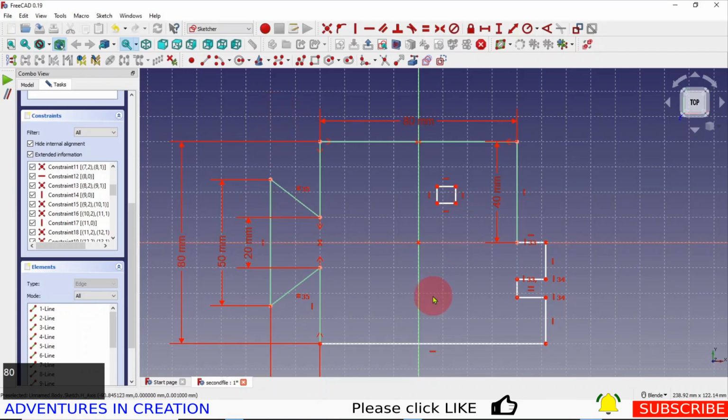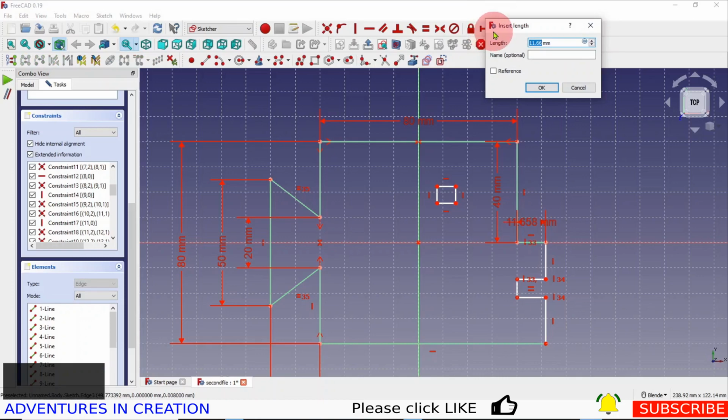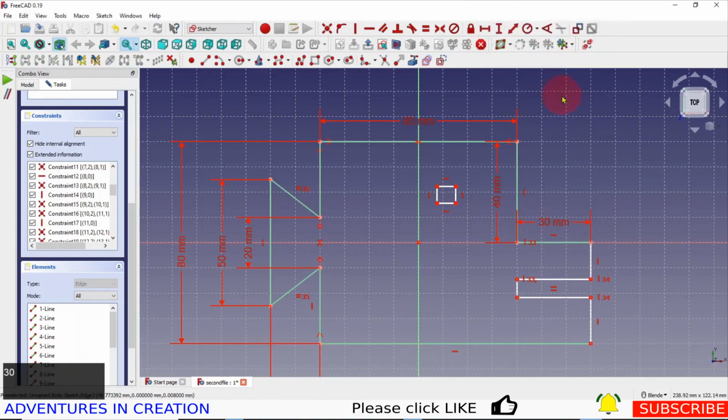So I've started to constrain the shape, and I have a dimension for this horizontal piece. It should be 30. And remember, these are vertically constrained, so it's going to move both of them together because of that vertical constraint that we built in there.